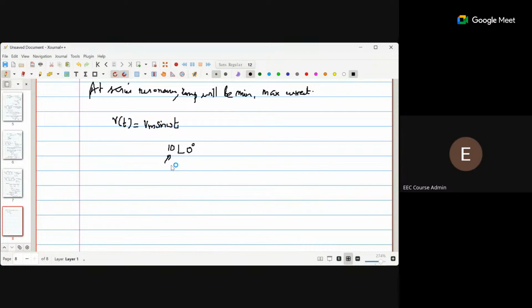Just like the case of diode, whether it is RMS or peak, mostly it would be specified to give you clarity. But in vector form, suppose something like this is given and nothing is specified, then by default this should be treated as the RMS value. But if it is in the time domain, the things are clear, this will be the peak value. So something like this in the vector form, don't treat that 10 as a peak value unless otherwise specified. If it is specified, you go accordingly. Other than that, you treat it by default as RMS. This has always been emphasized even in the corresponding live session, so I'm just reminding you on that.